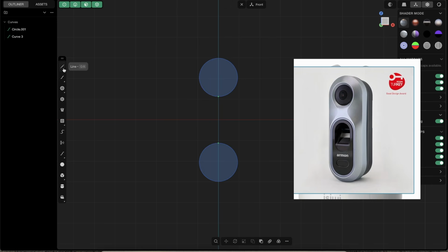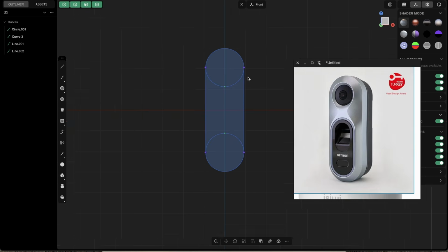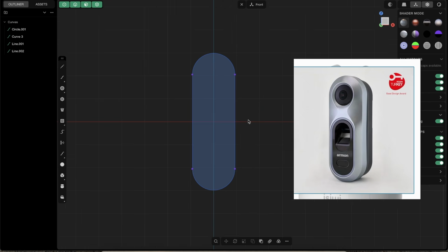And we are still in front view, create a line and just snap here on the 3/4 and make sure that you snap here where it says tangent, tangent. Right click, Shift A to again create the new line and just snap here 1/4. And again, make sure that you're snapping here where it's saying tangent, tangent. Perfect. And we don't really need those curves in the inside. So just go here to trim to the scissors or press T and just trim this guy and this guy away. Right click to confirm.